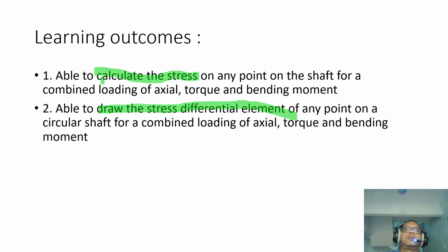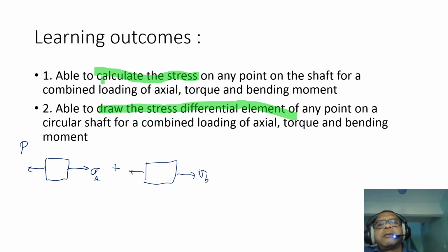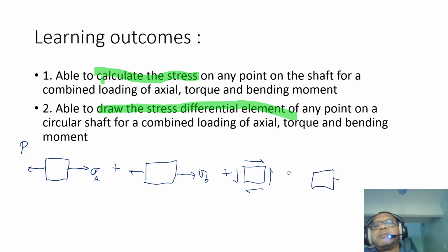So what I want you to do is just to combine for P, for example, take the axial stress plus the bending stress, plus the shear stress due to torque, to create your differential element.